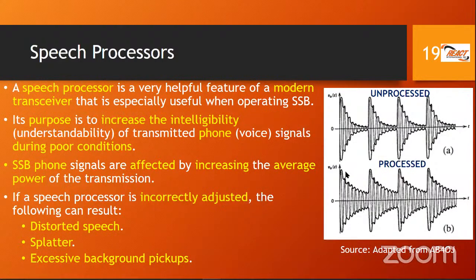But when you do that compression and you take your peak down a little bit, all of a sudden now, these lower frequencies here that you have, notice the amplitude, they are higher. They're shorter here, but they are higher here. It's the same speech, but you pass it through your speech processor. And because of this compression, what you find is that you have more speech going to your radio, and therefore your transmitter is sending out a higher average output power, just simply by changing your speech.